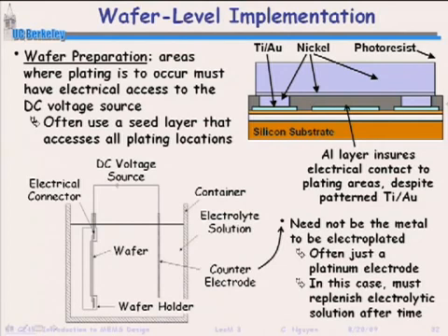And so this is what people use to do this. Same thing: you've got a solution, in this case nickel sulfamate, and you put it at the right temperature, you give it the right current levels, and you will electroplate different types of films with different current levels. So films with different types of granularity, some smoother than others. You pretty much have to figure out the right recipe to put down good films for MEMS purposes.